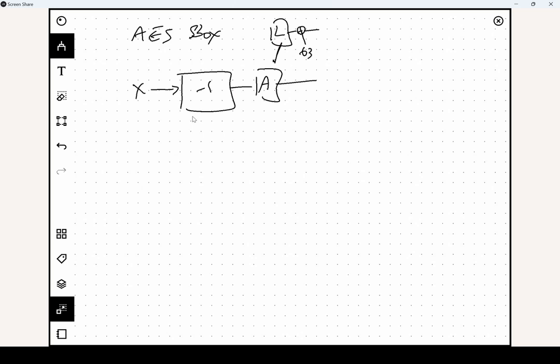If you write the ANF, the algebraic normal form, of the inversion, you see that almost every monomial exists in this representation. For that reason, if you just implement it using the ANF, it will be pretty large. If you ask the synthesizer to do it by a lookup table, it is also not as small. But what you can do, which is also given as a note in the original AES Rijndael design, is implement the inversion using a tower field.